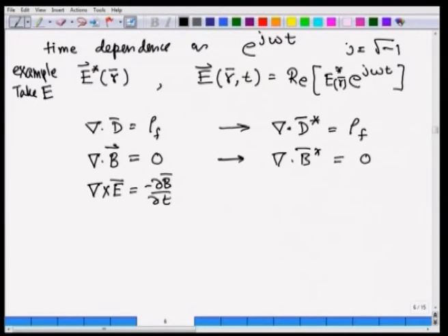Now the time dependence is coming, hence it is interesting. It translates into curl of this quantity E star, and remember what the time dependence is. How would you take the derivative? Remember, time appears only as e to the j omega t. So the time derivative we will write as j omega of the same quantity, since in the exponential it will recover the same quantities. Whenever the time derivative del t appears, a j omega will appear because the time derivative is taken in this form,